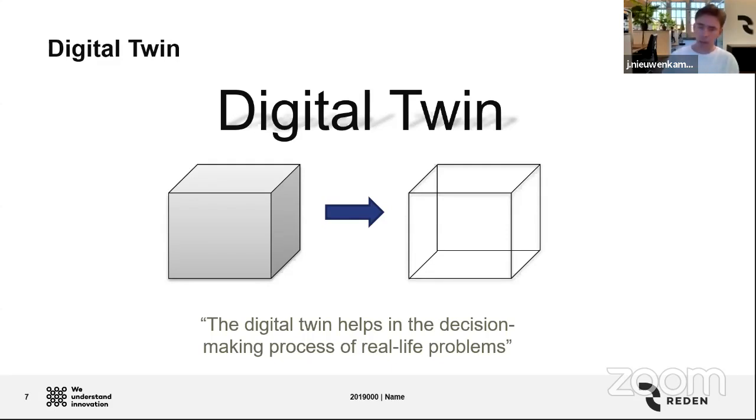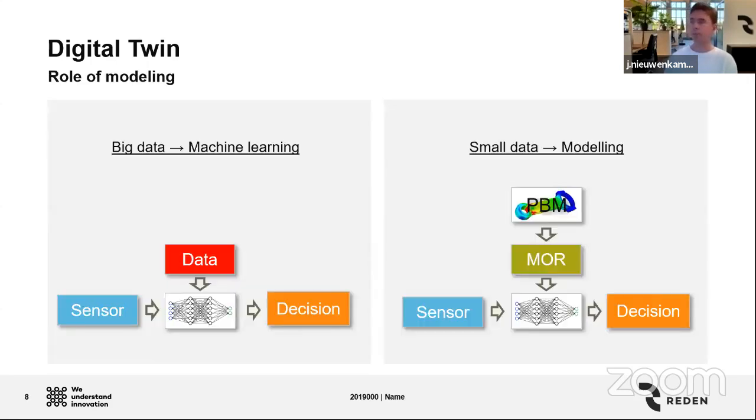For example, if you would have a digital twin of a bridge, and you would monitor in real life the amount of car or truck movements on that bridge, you could calculate within your digital twin what the stresses are in the bridge deck, for example, and determine when fatigue limits are there, and you need to do some maintenance, for example.